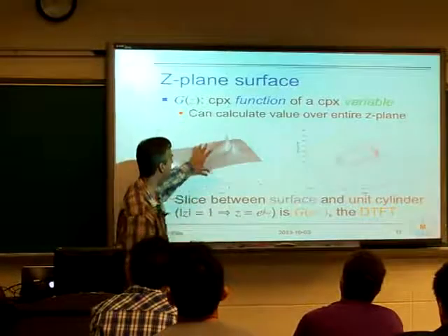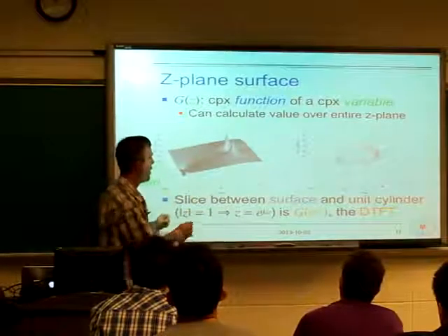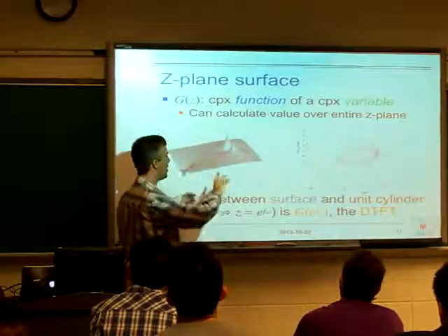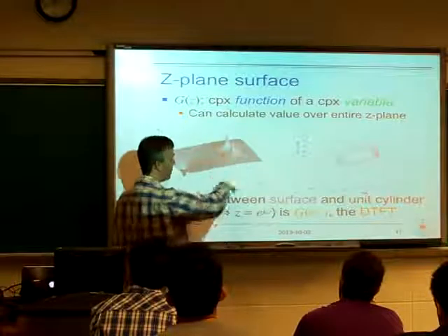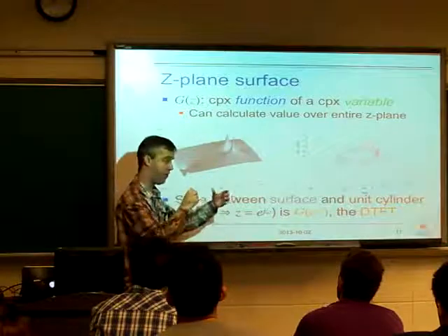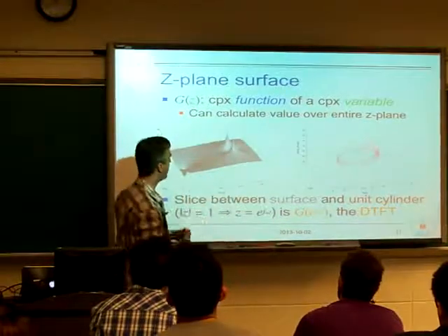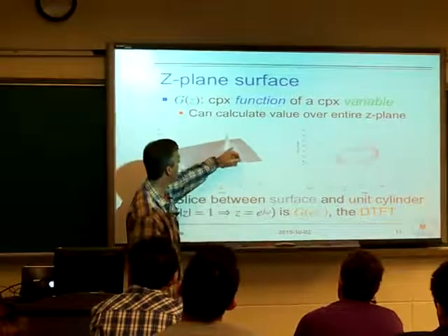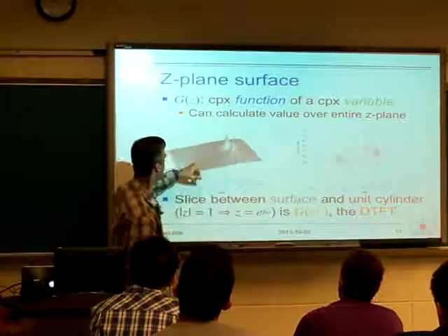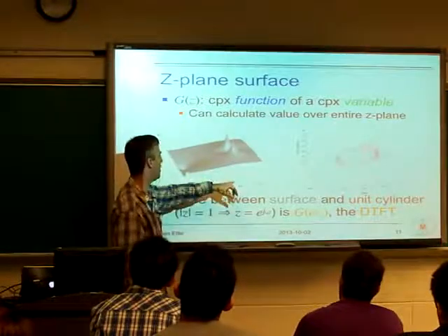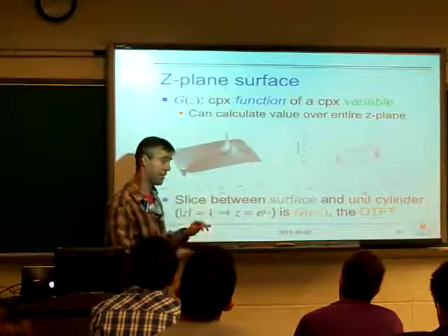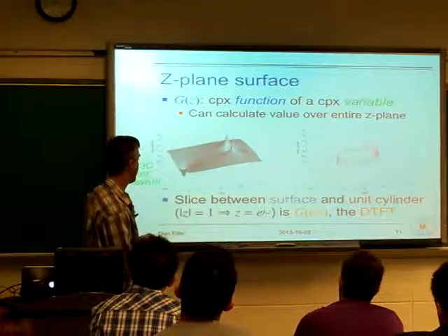But we get this entire surface. And this is what I'm saying about how it sort of works. If you know the position of these poles, then they have this influence, right? They basically have this 1 over radius effect on the magnitude. And so you can sort of see how the value of the surface at all points on the surface is determined by the relative influence of all these poles and zeros. And that's the only thing that's influencing it.